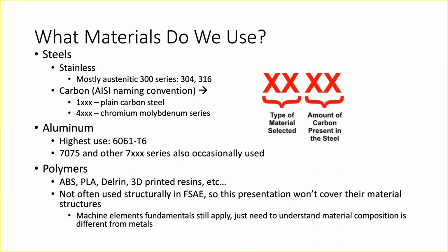So if I have an interface that is undergoing extremely high contact stresses, I might select a heat treat for steel that is extremely hard and is resistant to that kind of galling that I got on the surface, right? I want the hardness of the surface for many shafts is the primary consideration.